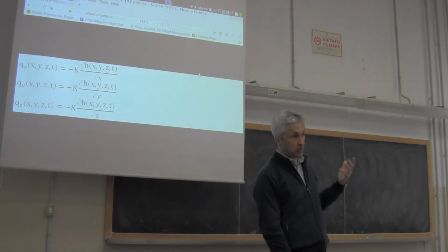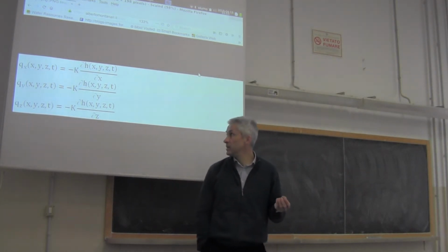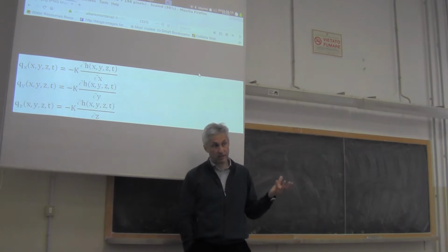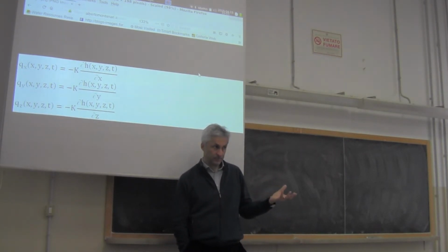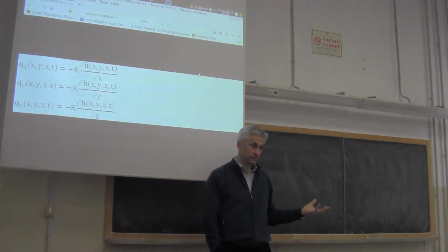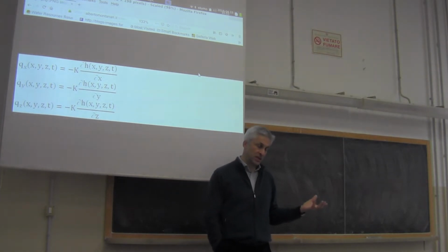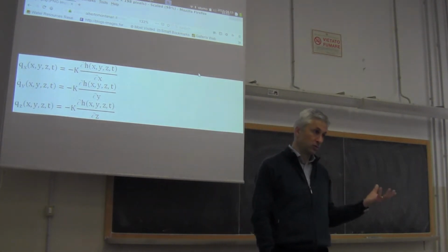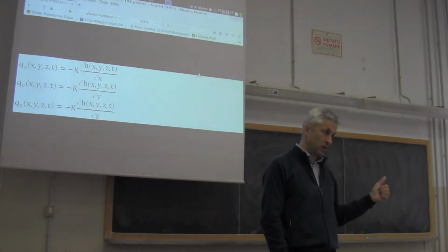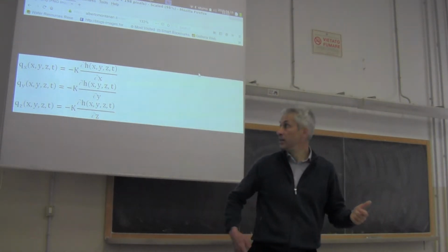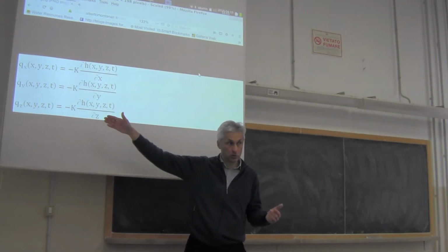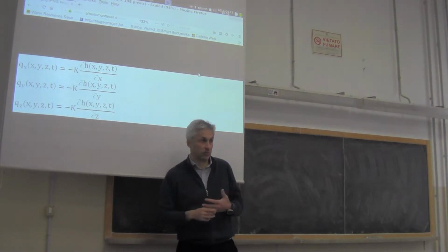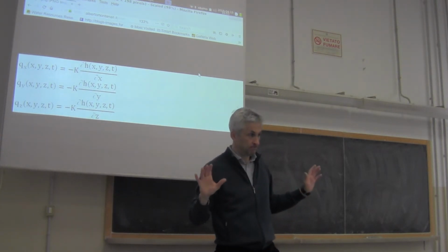So this is Darcy's equation that allows us to express Q depending on what? Depending on head. Which is precisely what we are looking for. Because if you remember, I said the continuity equation has two unknowns, flow and head. But if I can introduce now a second equation which relates flow to head, I reduce the number of variables to 1, which is okay.